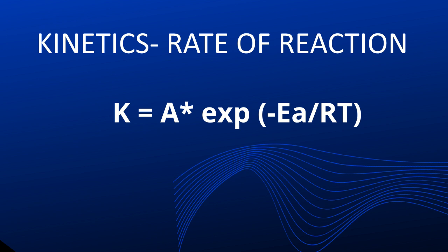There are two unknowns, Arrhenius constant A and activation energy EA. Here we fix the Arrhenius constant and calculate activation energy. However, the software also allows scanning activation energy for incremental values of the Arrhenius constant.